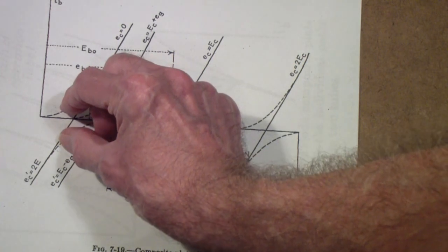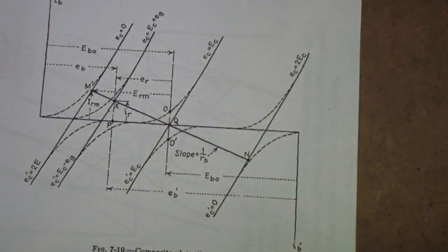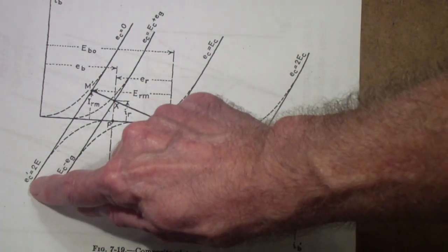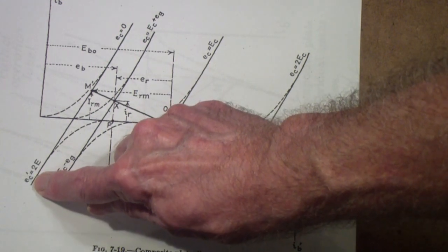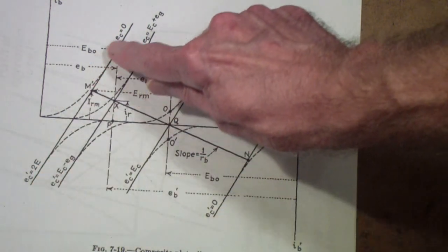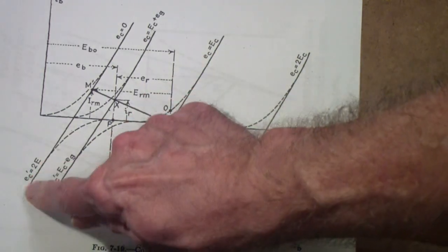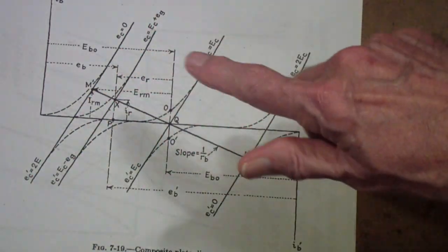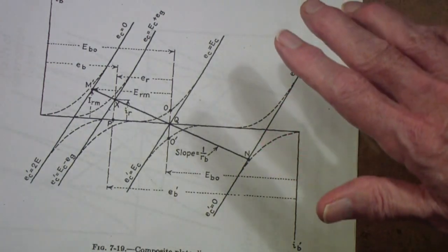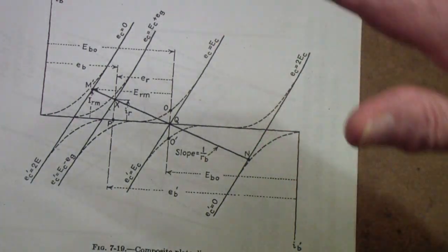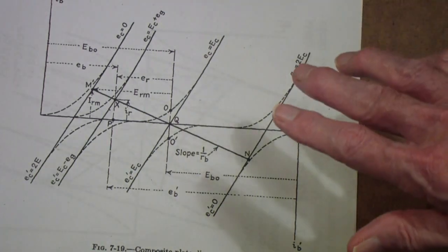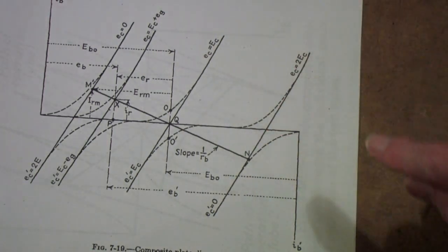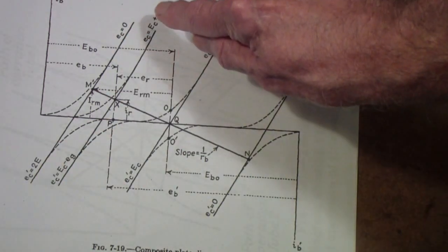It's as though these two tubes are linked to each other, and in a sense they are. They are linked through the autotransformer action. And the result is that the characteristic of that tube operating in conjunction with this tube causes it to be a relatively straight line. Now, understand, this assumes that your transformer is perfect. This assumes that your tubes are perfectly matched. No such thing really exists. However, it comes pretty darn close.